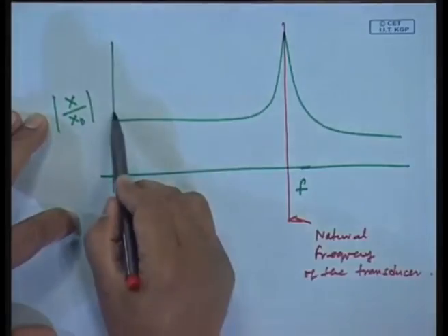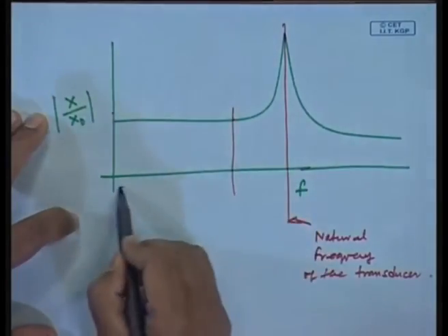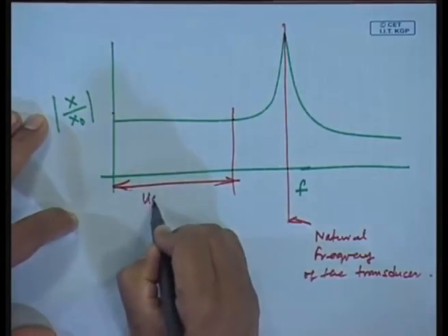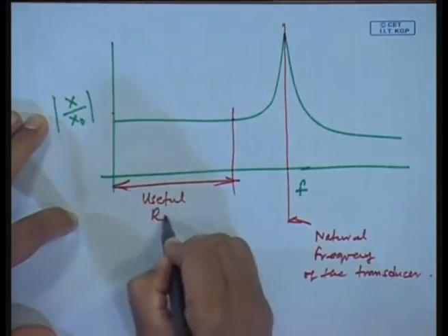So, I should be doing my measurements in a band much away from the natural frequency of the transducer. So, this is my useful range.